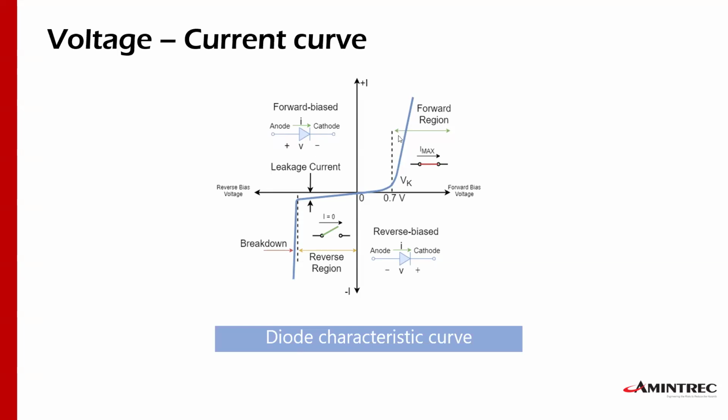When I'm over here, just pay attention to this. This will be the maximum current, which is very close or almost the same as the short circuit current, okay? So the short circuit current will be equivalent to the maximum current of a cell. So you could say that all cells, when they're not blocked, will operate with the short circuit current.